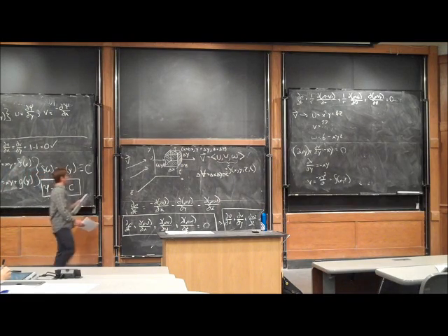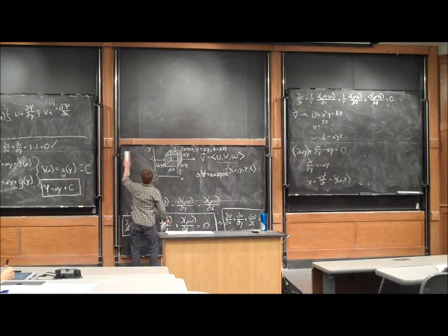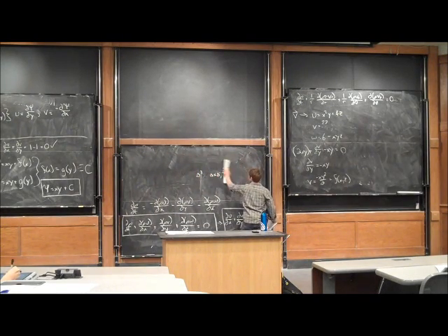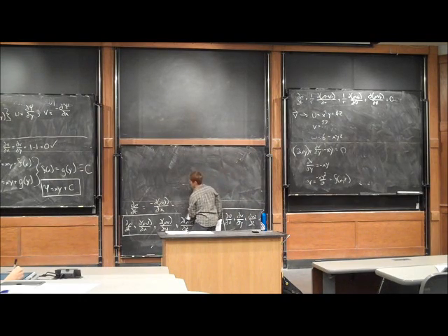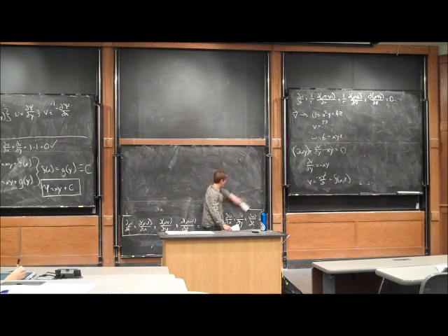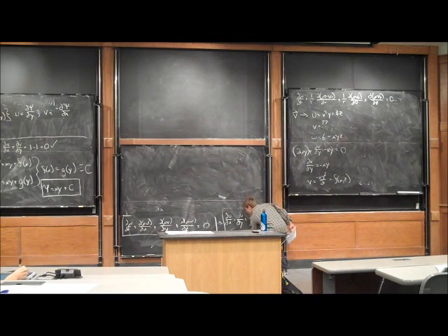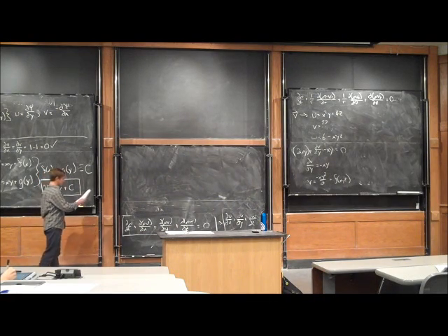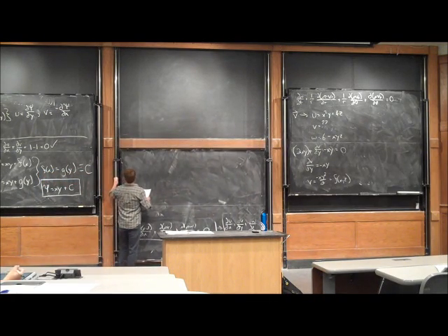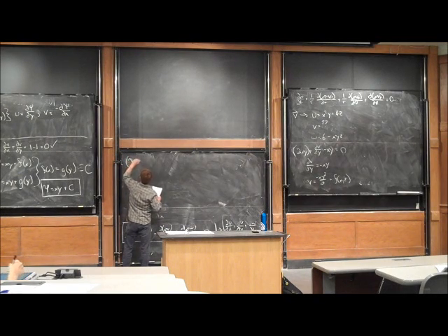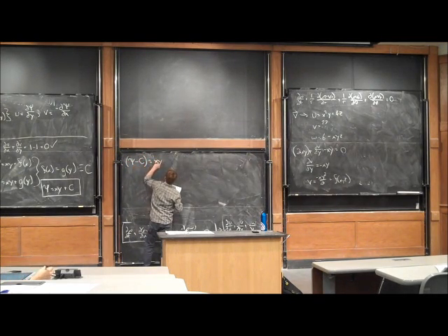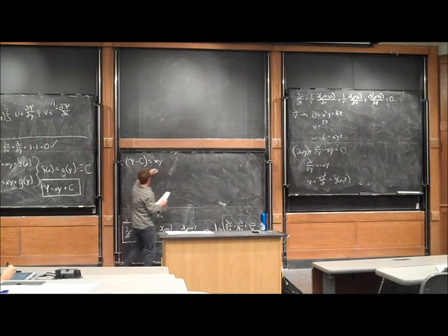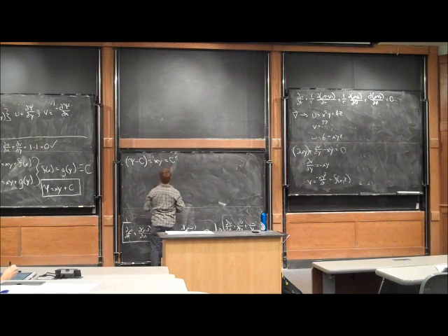So what does that tell us? That allows us to visualize what this two-dimensional flow would look like, because now we can set psi equal to a constant and solve for the streamlines at that location. So if I say that psi is equal to a constant, I know that psi minus c is equal to xy. So by picking psi to equal a constant, that's just going to be equal to some new constant, I'll call it c prime.